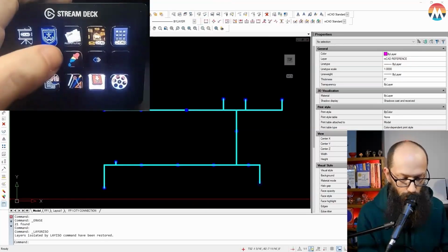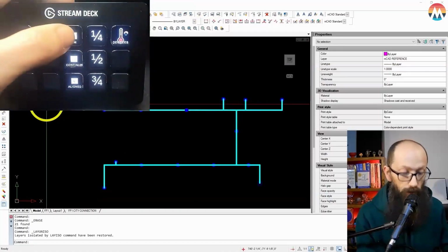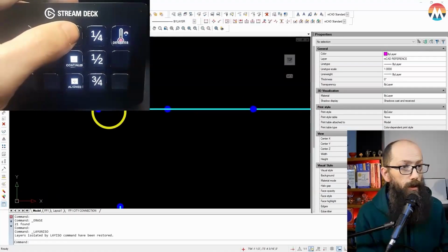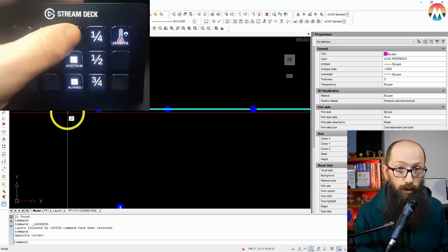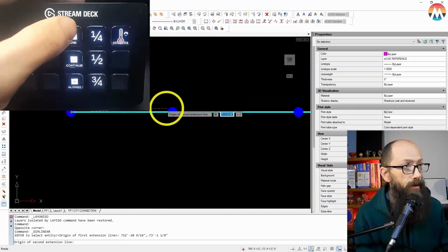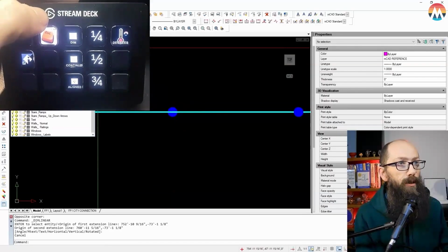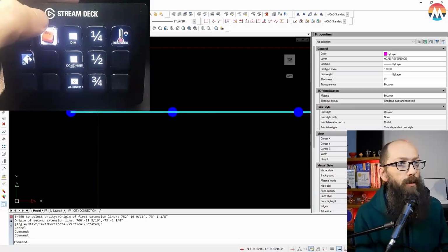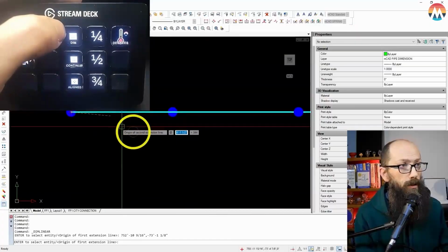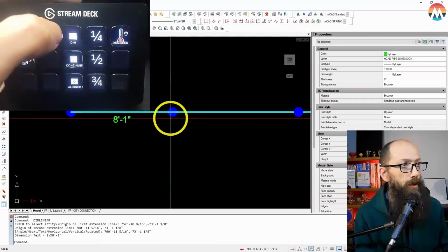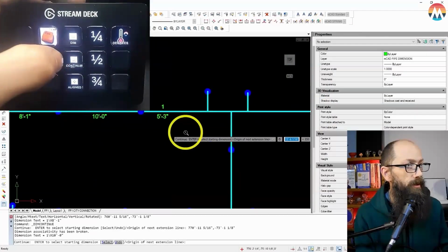Let me, okay, go back to my CAD tools. And now I'm in dimension. So I've got a linear dimension programmed in here. Oops, I got to actually be clicked into my CAD program for it to work. So dimension tools, linear dimension, now it works. So click once, click again. Oh, I got to change to mCAD pipe dimension and mCAD sprinkler. Now it'll work. Linear dimension, 3 points. Now I can click this button here, continue, and I just keep going.